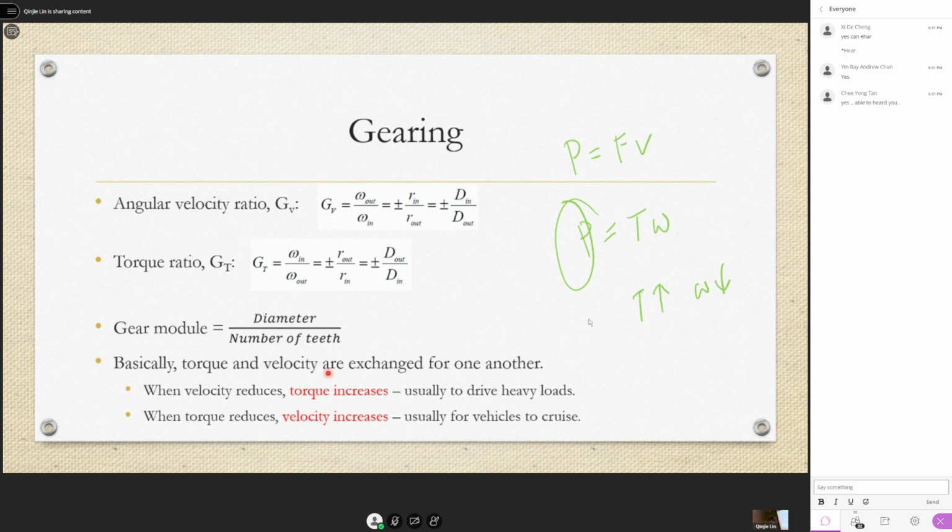But when you do that, as you lower and lower the gear ratio, going to gear 2, gear 3, the gear ratio decreases to match the wheel speed. What happens? The torque decreases. So if you go up to gear 5 or gear 6 and try to accelerate, you can depress until the end and you won't get much power increase, because that is when the engine transmits the lowest torque, so that you can have the speed.